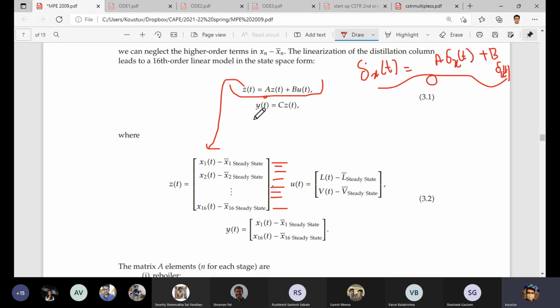And then we have one more relation, which is basically y related to z, because z gives us the liquid composition changing as a matter of this unsteady or transient behavior. The different terms that are contained in the A matrix and B matrix are evaluated, and those are nothing but the coefficients of the first derivative, or the Jacobian, calculated at the steady state point.